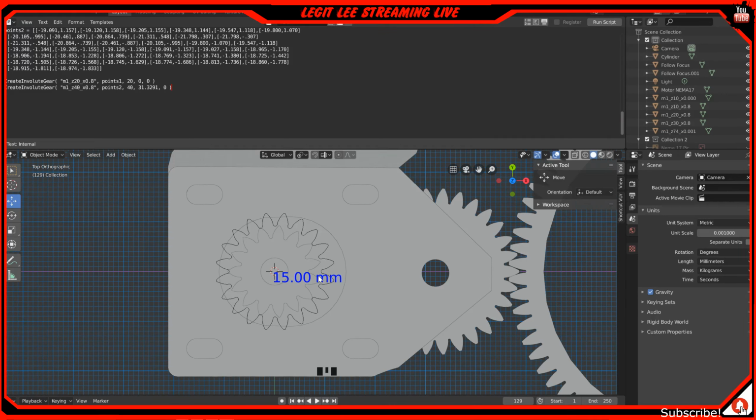So but 20 seems like it's okay. We could even do a 30 tooth. As long as we're not hitting anything in here, we may be able to reach it. A 30 and a 30. So that'll be a 1-to-1. So we won't have to worry about the gear ratio on that one. And that helps with the speed. We're not going to have a lot of torque, but that's fine. We can try that out. 30 to 30.